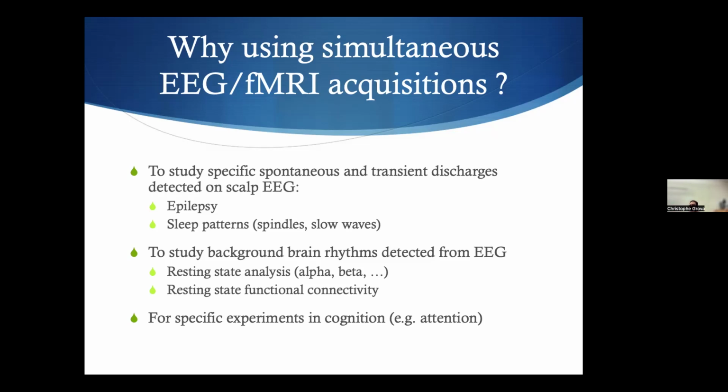A key idea in EEG, when you start, is always to look at your signal. Because if you have a very strong artifact, a very strong noise, let's say muscle activity at that time, it might create a huge envelope over there and you might completely be misled. So if you see that in your data, this would probably be a part of the data I would remove.